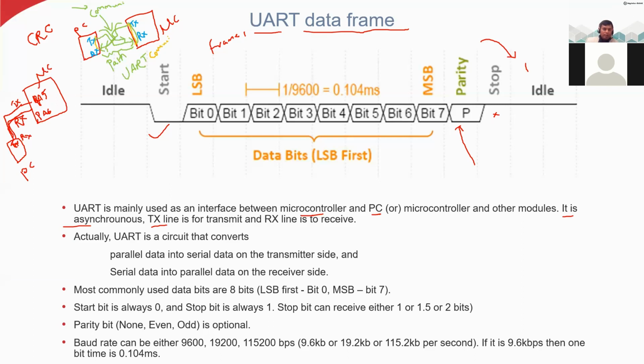So what the UART interface is doing is converting whatever data we want to transmit into serial data. Let's say I have the number 1. If I represent that in 4 bits, it is 0001, or in 8 bits, 00000001. This data is coming to the transmitter pin, and you cannot transfer all these data in parallel, so it must be transmitted in serial.